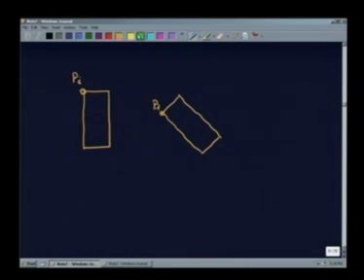So, this point's displacement is this, and if we just subject this body to a pure rectilinear translation, then the position of this body would have been like this. So, this is a pure rectilinear translation of the body from the initial to the intermediate position, and then keeping this reference point, whatever I have selected, we give a rotation to the body from this position to this position.